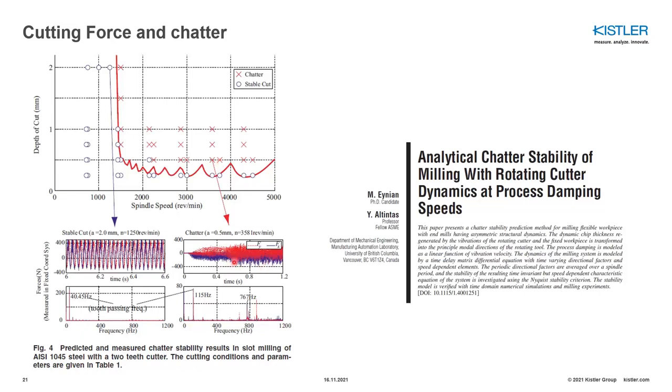Then, of course, you have a wide spectrum of representations between these two. So this means that when you look at a force measurement, you also see the indications of oscillations starting up or heavy oscillations. So the noise, or the dynamic part of your force measurement, can give hints about the chatter and oscillations and so on.